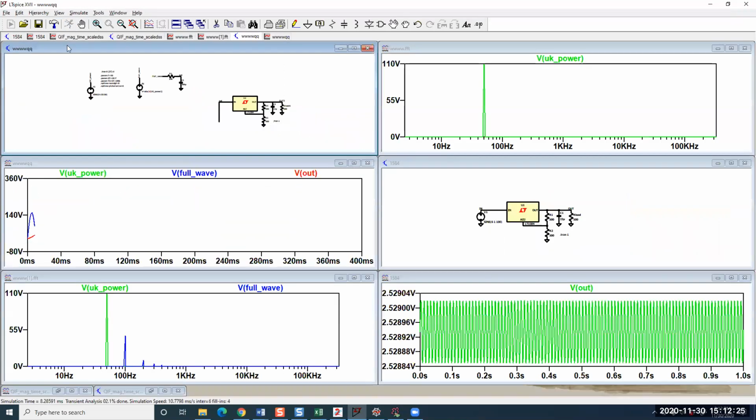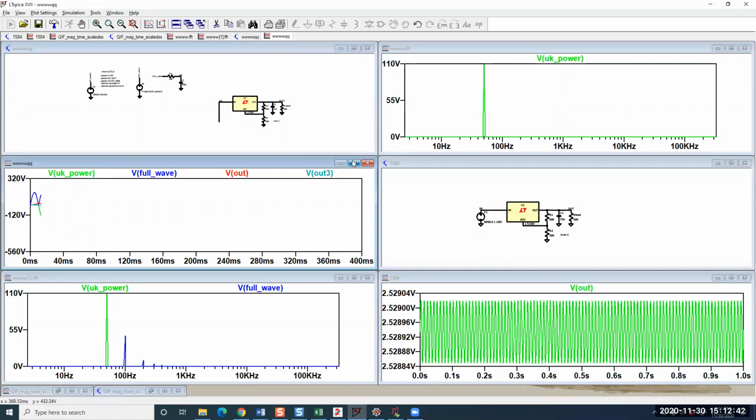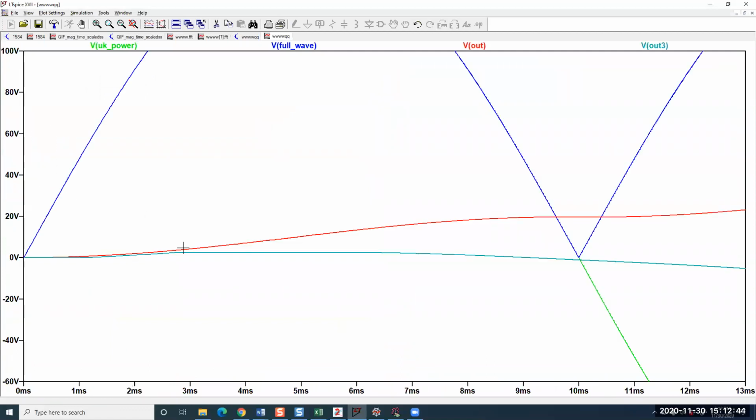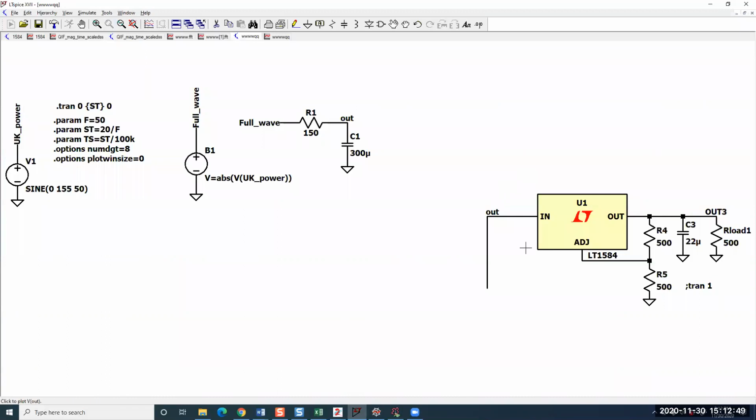But what happens when we run it, it starts getting really slow, and acting, you might say, very peculiarly. And that is because the maximum voltage for this device is 7 volts, and we're putting in 90. And so Spice is just having a hard time with that.